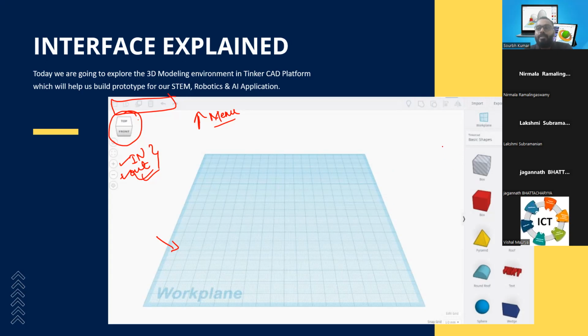So we have the shapes segment in here. Through the shapes segment, we can bring out those structures which are already predefined, using logical conclusion, right? Suppose we have a cube-like structure, we just import the cube-like structure into our design, and we try to merge a cylindrical object in between.